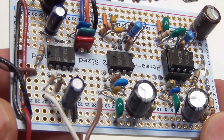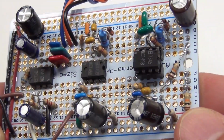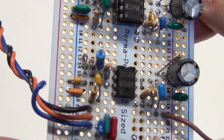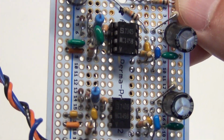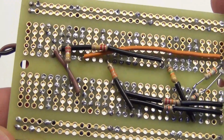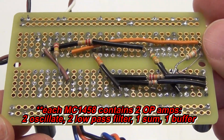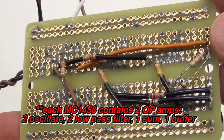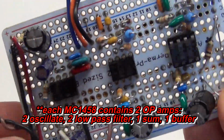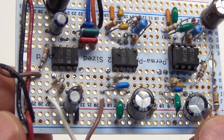And here's that 2-tone audio board that I mentioned. It is a bit cruder than the double balance modulator. As I mentioned, I just used a piece of perf board, scrounged around in the junk box, and whipped this up in just a few hours. The construction is pretty simple. There's 3 op amps there. They're MC1458s, and 2 of them are doing the oscillating, 2 of them are buffers, and then the last 2 are combining the signals and also buffering the output. So pretty straightforward. And like I said, you can find the schematic for this in EMRFD.